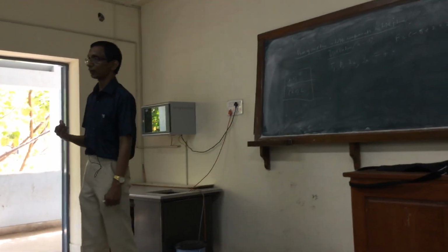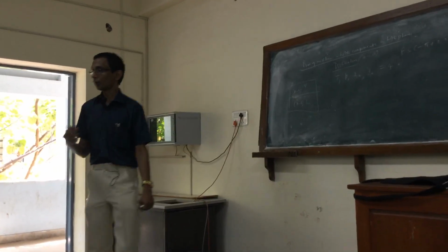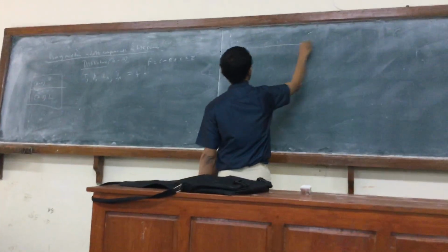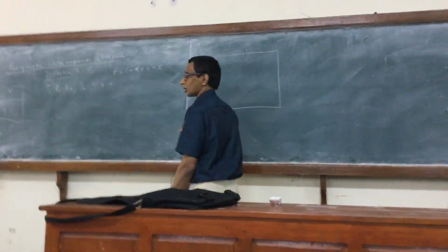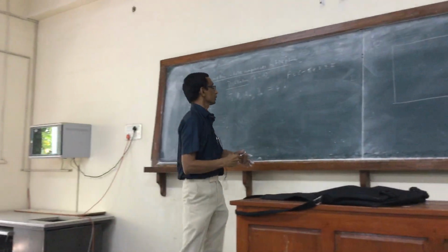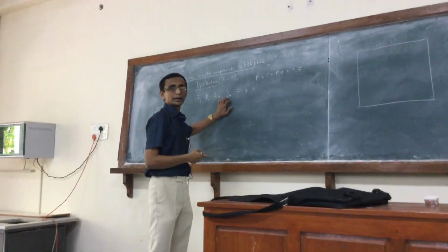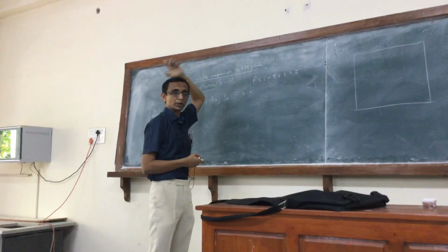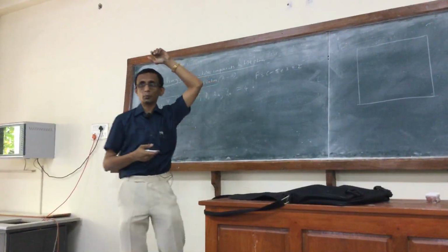So let's now look at the representation of the phase diagram. It is typically presented as a constant pressure or constant temperature section. Because if I have to plot this, two of the variables are independently varied, and the other two, if I had to plot, it would be a four-dimensional plot.